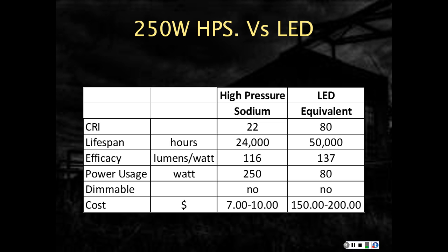So we're going to compare the same categories. On the color rendition index, high pressure sodium is poor. It's not 0 like low pressure sodium, but it's only 22. The LED equivalent is way better. We're up to 80 on the color rendition index. So LED wins that battle.